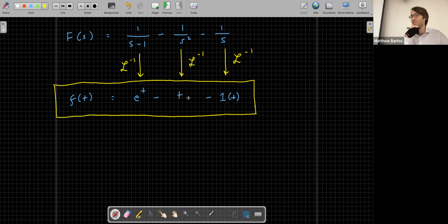Right. So we'll talk about what the definition of stability is for the purposes of this class. But if you have any term with a repeated root, you'll end up with a term that can potentially grow over time. So your system will not decay to some steady state. It won't decay to 0.